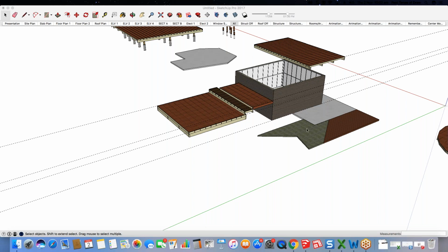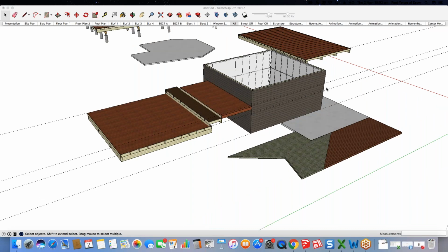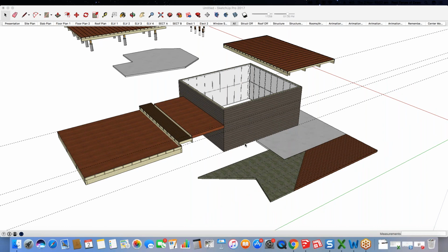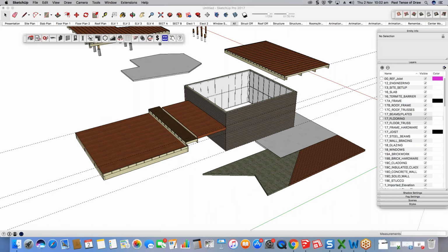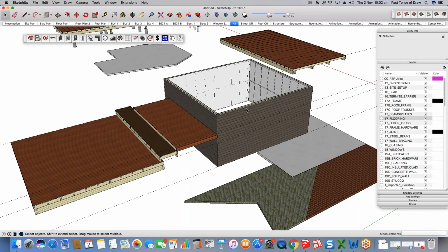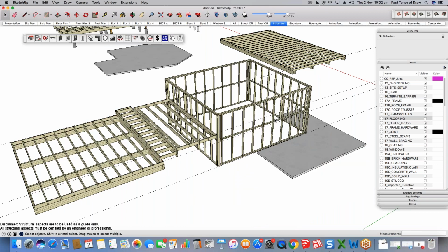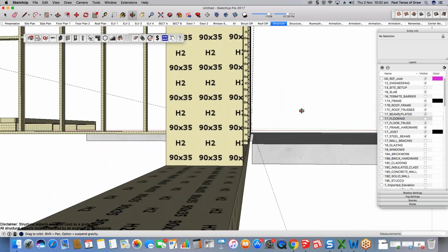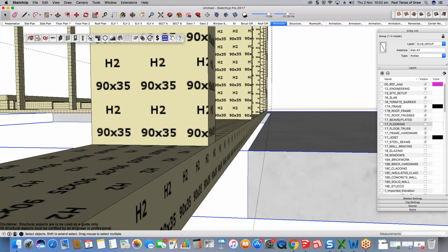Can you turn the cladding off so that you can align the floor structure with the wall structure, not the cladding? Oh, 100%. That's part of the advantage of being able to model in structure, and that's why we believe structure is so important when you're designing, modeling, or quoting. Users should really get used to modeling in the structure scene. The reason is that often you don't ever want it to go to the finish, like what I've done even here. You're actually wanting it to align with the structure more often than not.